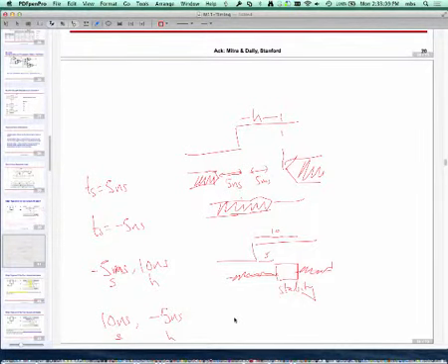This is the hold time. Then what this is saying is, relative to the clock edge, it should become stable at the edge minus 10 and remain stable through edge minus 5. And that would be the case with a negative hold time.